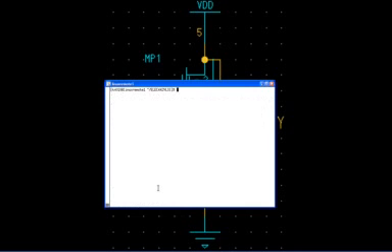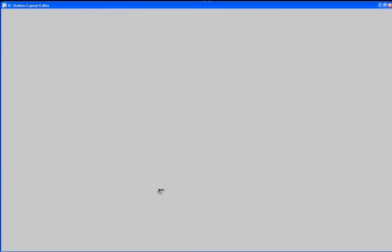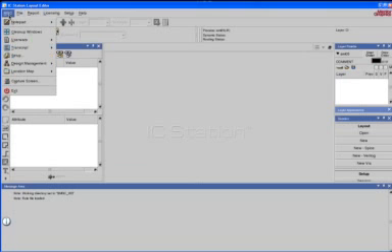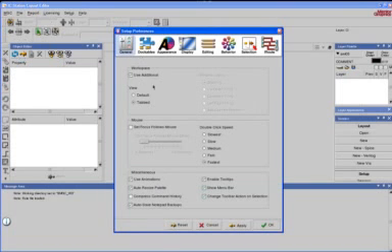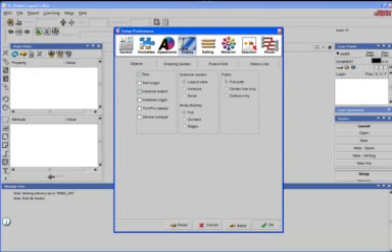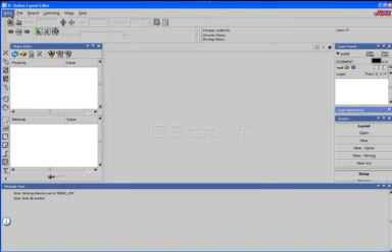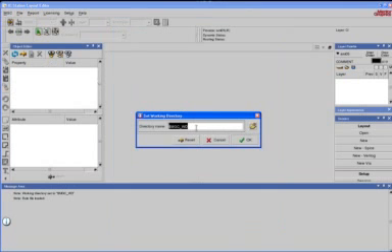Now on the Linux prompt, type in adk_ic and the ampersand. This will bring up ICStation layout editor. First thing, let's go and look at some of the setup options. MGC, click on setup. This brings up this window. Click on the display. Under display, click on rulers grid. Make sure your snap grid is set to 0.5. Grid points at measured, you can leave it at 5 or change it to a 6. Hit apply. Say OK. Also, make sure, go to MGC, location map, set working directory, and you can leave it at MGC_WD.